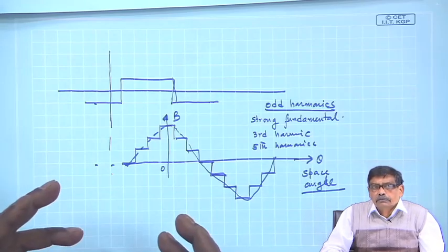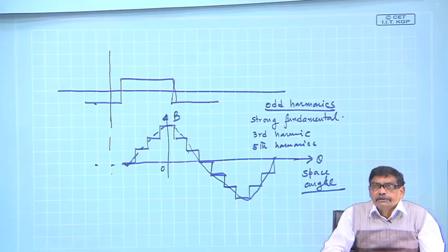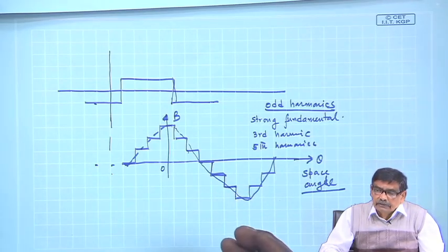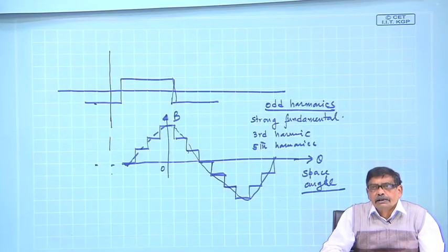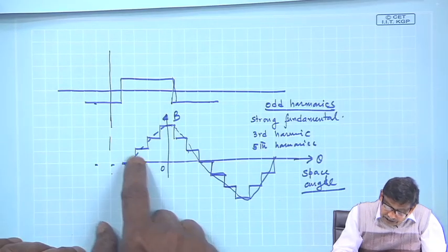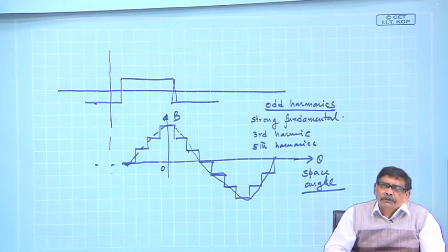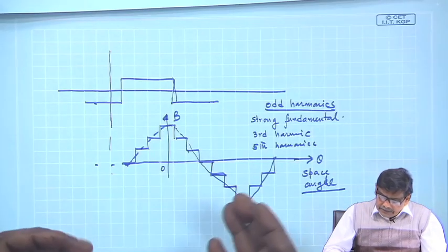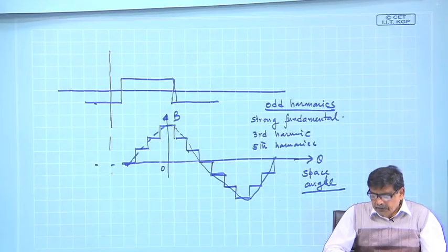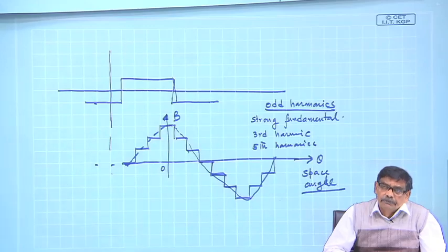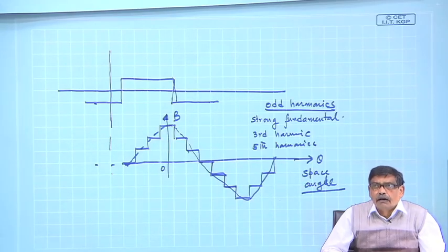if you take a generator mode of action, then rotor conductors, if moved by a prime mover, will have a voltage of this form only, but I am telling you that the voltage will be closer to a sine wave. And there are methods, by selecting the span of the coil etc., by which you can reduce even a desired harmonic.